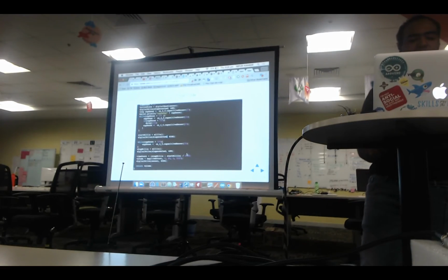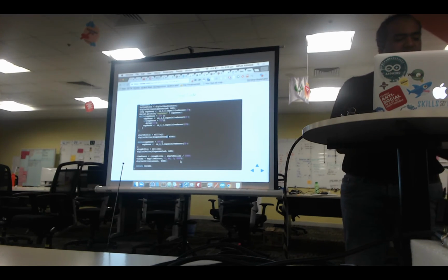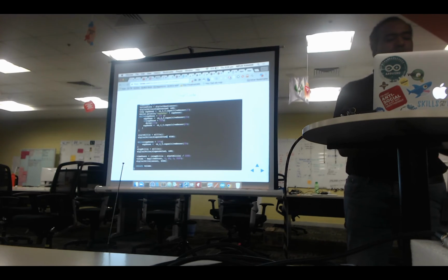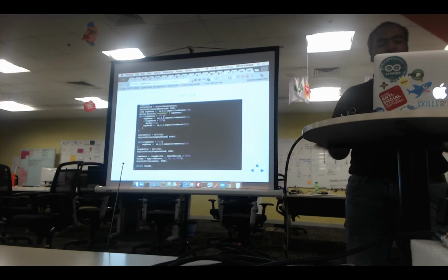We stop the timer and then we count the time between the stop millis and the start millis. Then there's a map function in the Arduino, where 0 to 99 would be mapped to 0 to 1000. So in seconds, we assume that you won't be standing there filling more than 3 liters of water. So 0 to 99 seconds would be mapped to 0 to 3 liters. That is it. It returns the volume.